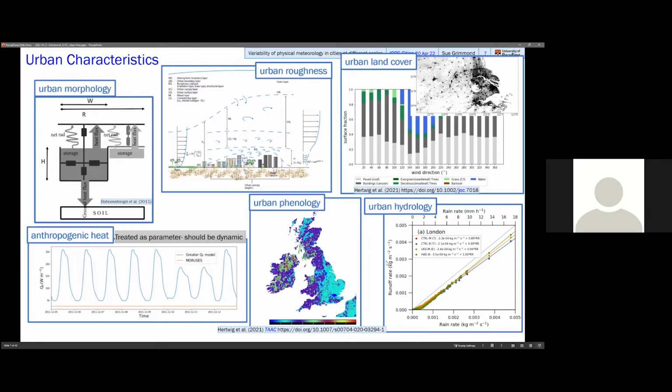So if we're looking at urban or built surfaces, then often rainfall will be lost from the model within one time step, and they could have no external water use, so garden irrigation, street cleaning, or water used for dust suppression is not actually included. So both of these, the fast runoff processes and also the lack of external water, will impact the soil moisture, which will again modify our latent heat flux and carbon dioxide flux modeling.